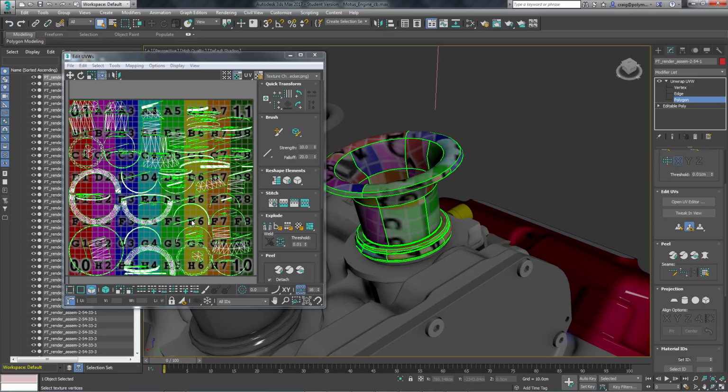It's important to understand that I'm going to show areas where this wouldn't work, but there are cases where automatic UVs are going to get you there. Sometimes there are objects that are not texture-based, and for the light maps, what you need them to be, this may work out perfectly fine. And if you have objects that are going to be a specific material, an automatic UV layout like this may work just completely fine for what you need. And you saw how quick that is. I just drop down a modifier, do a flatten map, and hit OK, and we can get results rather quickly.